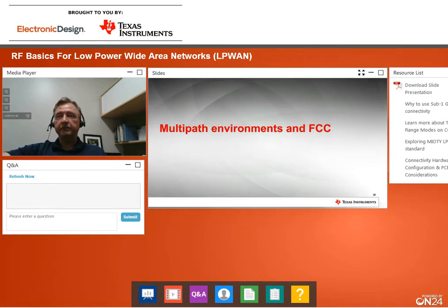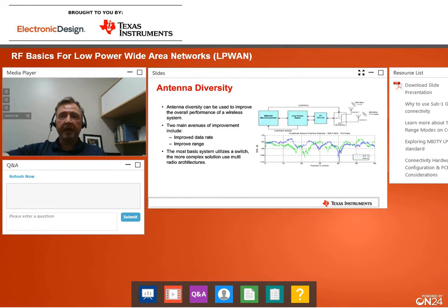There are a couple of key considerations also for other RF networks, and I will just go through them quite quickly here. So multipath is very important, and this is the thing about that. If you have a network that has a fixed installation, you can actually be in a null just due to the way that the signals are either constructively or destructively interfering.